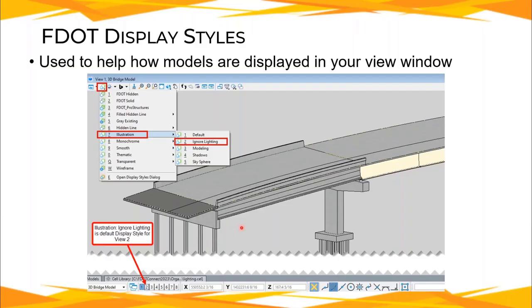You can check that in the 2D wireframe, and there's certain things that are good about checking it like that, but it's a lot quicker and easier, at least for your first review, to turn on the illustration or lighting displays file, and look to see how the other disciplines, more so the roadway corridors, are interfacing with ours. You're going to see real quick that things are lined up horizontally and vertically in this particular view.